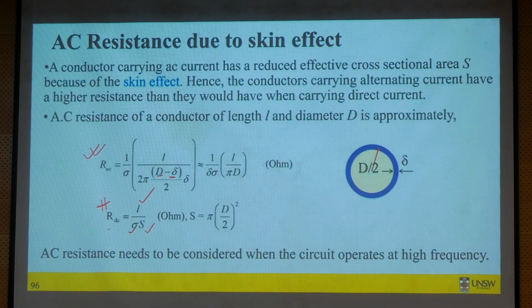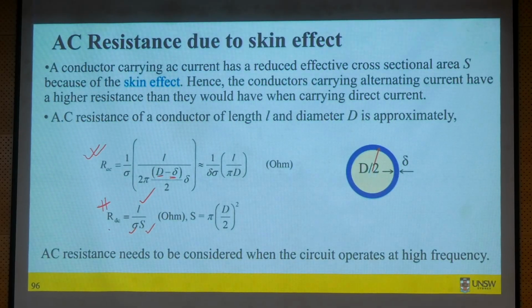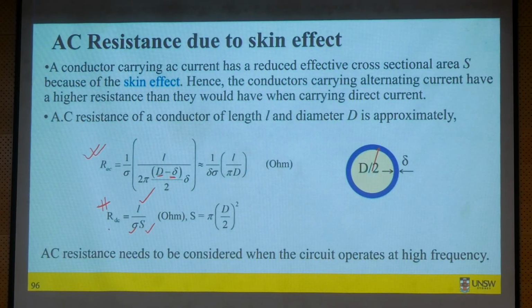Will its harmonics see high frequency, and is that going to cause some extra losses, especially in the AC resistance? AC resistance is also a concern for the hairpin winding.